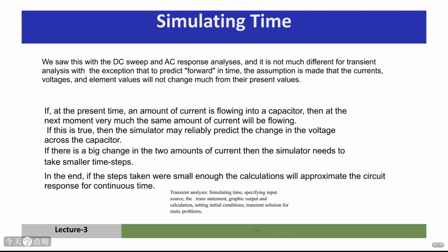How does transient simulation work? It's based on numerical integration. The simulator predicts the future state of the circuit based on its current state. It assumes that the circuit doesn't change drastically between the current time step and the next one.